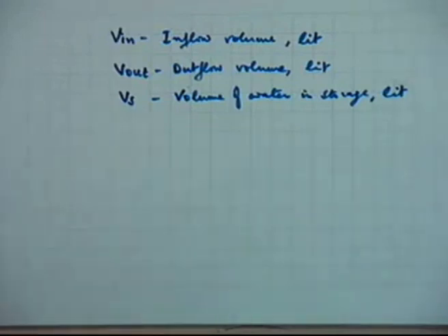So this is basically an inflow-outflow analysis. If you start the analysis at a particular time and take the final value after a very long time, what you get is the average value of infiltration over this period. To find the variation of infiltration over this segment, you have to take some intermediate observations. So you keep taking observations at some interval so that you can find out how the infiltration was varying over time.